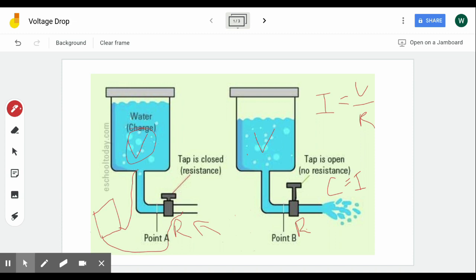In this case, we would be seeing a pressure drop equal to the total voltage. So let's say our voltage in this case is 12 volts, sticking with the car battery theme. The difference in pressure that we're going to see between this point and this point is going to be our full voltage of our battery. So in this case, when we take that measurement, we're going to see 12 volts of potential or pressure.